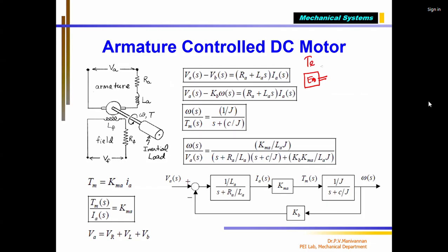Engine torque, I say TE, is what is produced due to the combustion pressure, the downward force, all those things. That will not be fully available on the shaft. Yes, the engine shaft torque will be still less. There is bearing friction, and also piston friction, all those things will consume some amount of it.